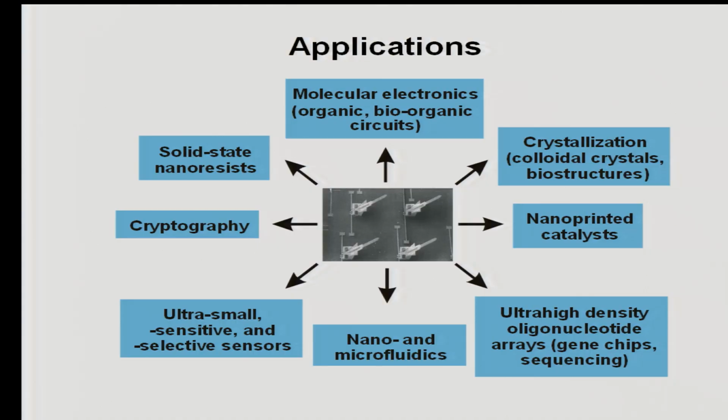Now, one of the big applications we did was we developed a sensor for detecting explosives, for example, which you can put in an oil refinery. If your critical gas concentration, your hydrocarbon concentration in the ambient, exceeds a certain value, you can shut everything down before an explosion happens.